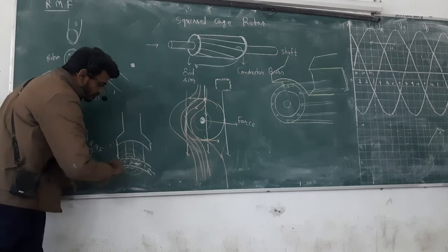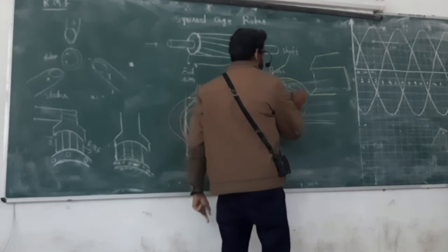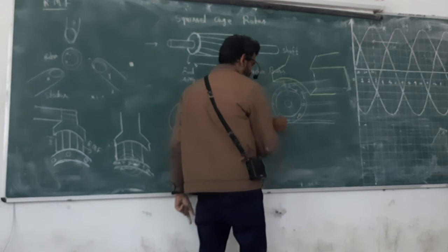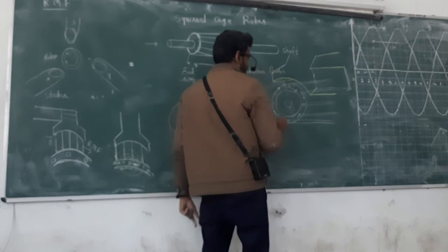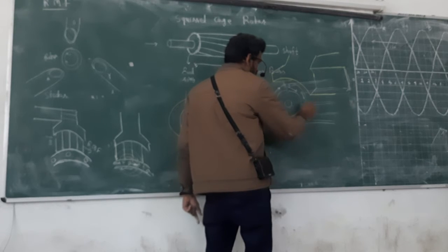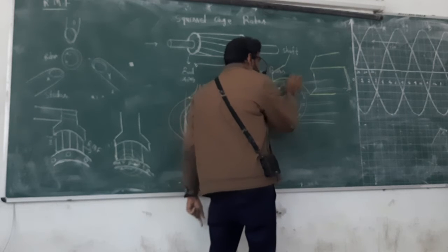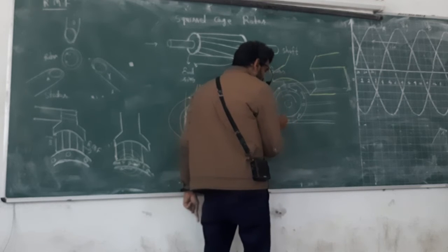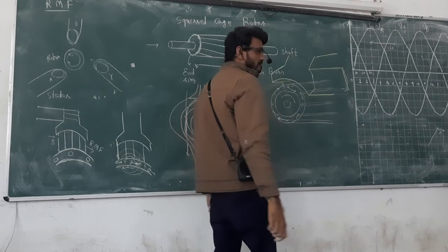So all the force on the conductors will give rise to the rotation. So we can say that each and every conductor has this kind of force. Here is a 0 force. Okay, then the force increases. Again the time comes that it is reduced. Here is this direction. If 2 poles are there, okay, and in this way the rotor will rotate in this direction. Because the conductor experiences the force in this direction, this conductor under that pole. Another conductor here under the second pole will experience force in this direction. You add these 2 forces, and the rotor will rotate in this direction. That is the omega.